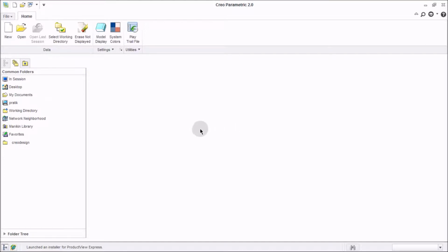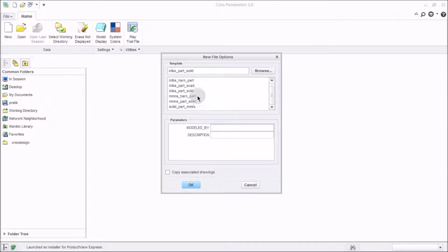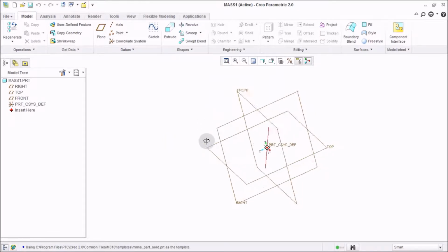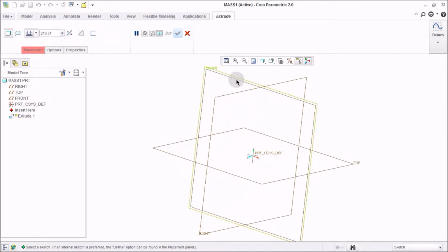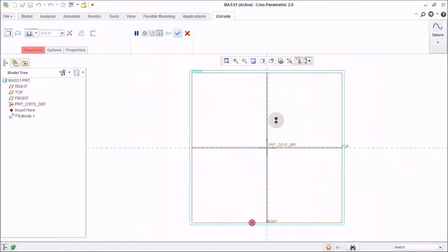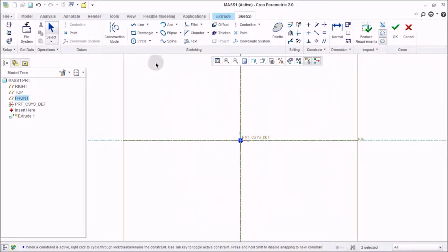Okay, first of all we make the mass, so name it mass 1. Then choose the units you want to use to create your part. I am taking millimeters right now. For simplicity we use only an extrude command and make the part a rectangular block. Make a habit of drawing a center line first, so you can easily identify where your coordinate point is. First we make a 100 mm by 100 mm square.